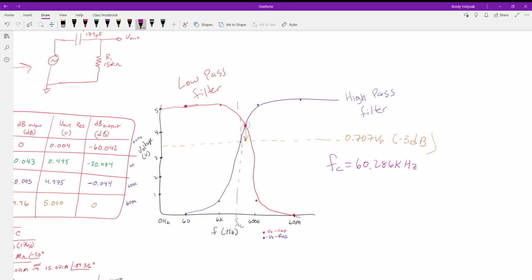I've got to double check on that, but that's the frequency that you're tuning to. So what you've done is you've tuned your radio to only pick up a small range of frequencies above 97.3 and a small range of frequencies below 97.3, and everything else is being filtered out so it can't be amplified and then pushed into the speakers of your car. And so that's the whole idea of these.